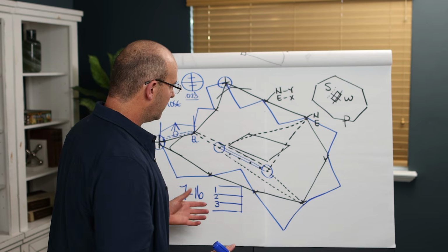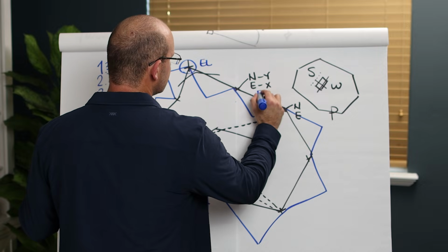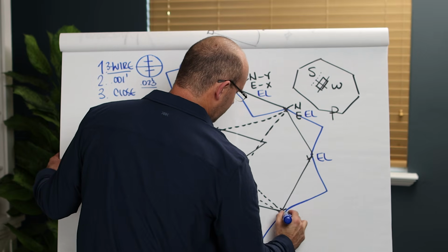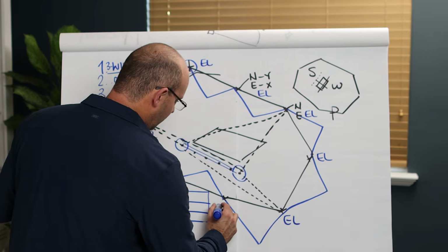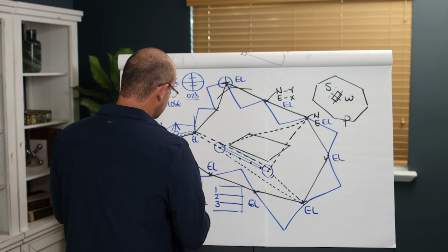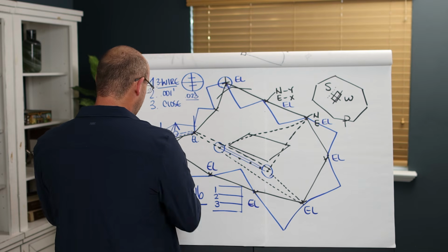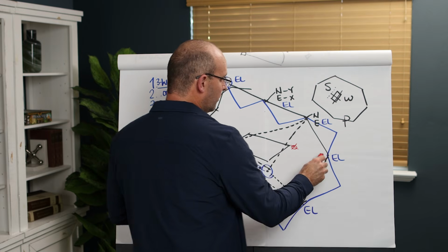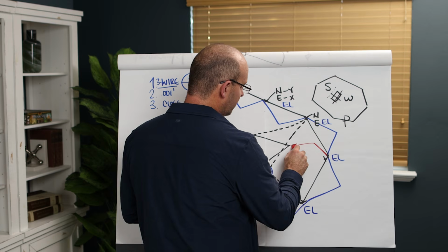If you're within that tolerance, now you have elevation on all of these points. In addition to your northing and easting, you have your elevation. And the reason you need your elevation is because you want to reference it for any additional control. And if you ever want to bring in another benchmark inside the site, like let's say I want a temporary benchmark in here, you will go backsight, foresight, okay?